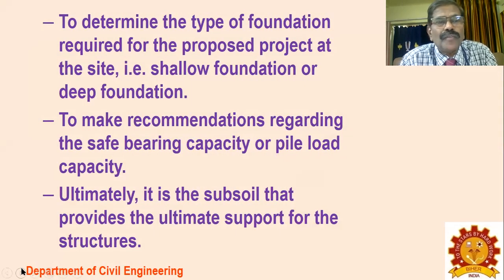To determine the type of foundation required for the proposed project at the site, the shallow foundation or a deep foundation, you will arrive at depending on the bearing capacity of the soil. To make recommendations regarding the safe bearing capacity or pile load capacity, you need to know about the subsoil. So ultimately, it is the subsoil that provides the ultimate support to the structure. So a thorough investigation or in-depth understanding of the subsoil and the underlying soil on which the structure is located, all those things are very, very important to look upon.